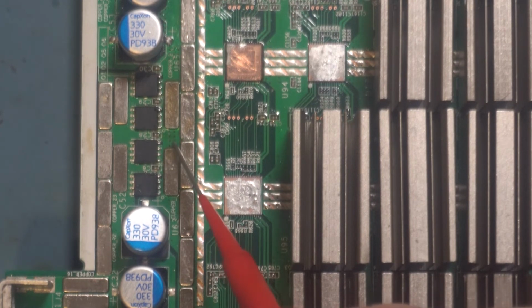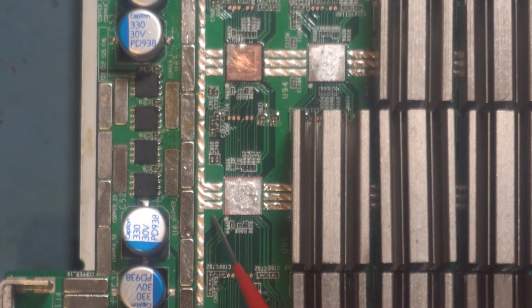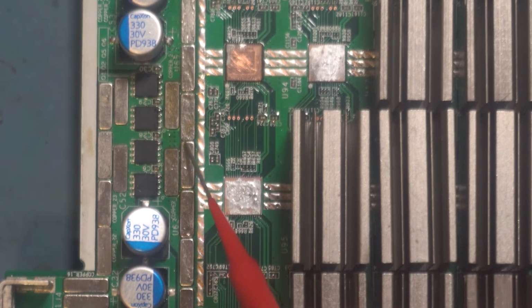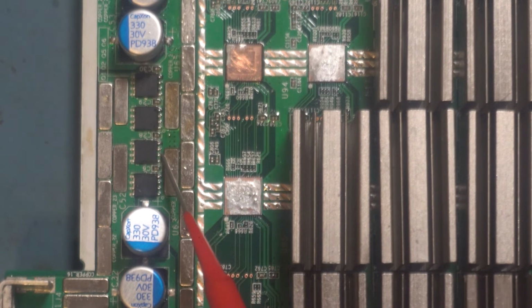And if you were able to see the copper traces, it's a little bit harder to see on video, but you see this line here. This lighter green is where the copper is, and this whole area is all the same piece of copper. My point is that this output is really what feeds the main positive, right? This is the end of our chain of domains, where the chain finishes, and this is the most positive end, which is fed directly through the MOSFETs.